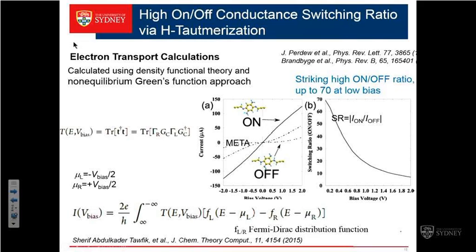Okay? These are some equations. I'm not going to go into explaining them. They were developed in these publications here. But what you can see is this is the current through the device as a function of bias voltage. And if you look at the first configuration, you can see, as you might expect, the current just increases as you go from, say, about -2 up to 2. But when you calculate the current-voltage characteristics for the other state of the molecule, you get this dotted curve here.